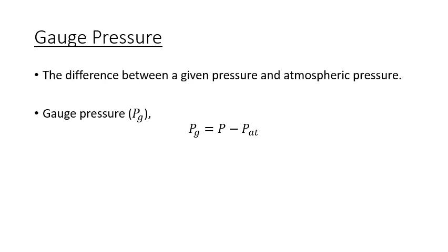The tire is at atmospheric pressure. And if the tire pressure is given as 30 psi, that means you have to inflate the tire from atmospheric pressure to 30 psi to have the tire fully inflated. So we are usually considering the pressure difference in these cases.